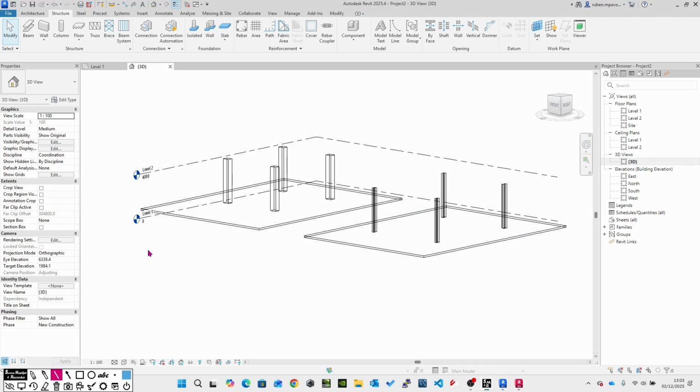And what I mean with the analytic model, well, you have to know that not all the architectural elements have the possibility to be exported to a BIM software related to structural calculation. So, what is the analytic model? The analytic model are the lines that Revit is adding into the center of the elements or into the perimeters, and they are lines that are quite common in structural calculation software.